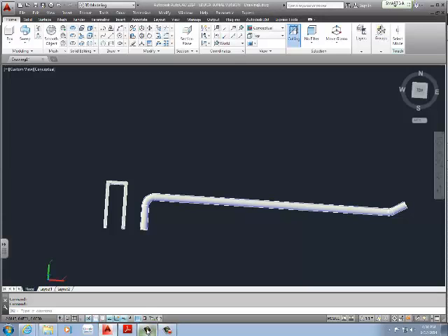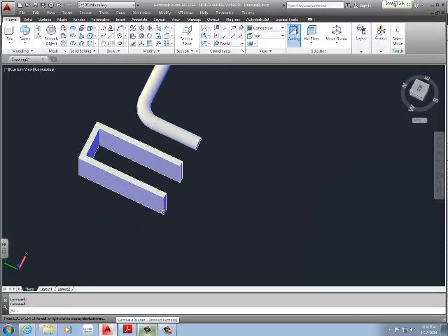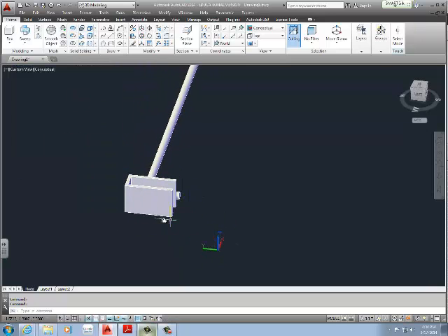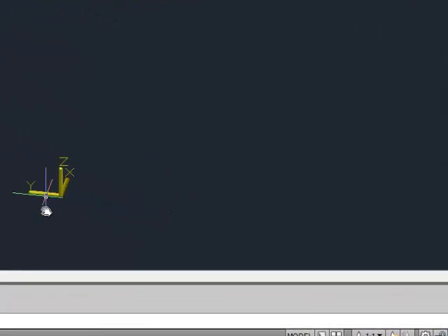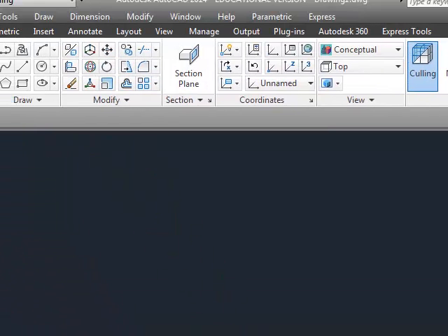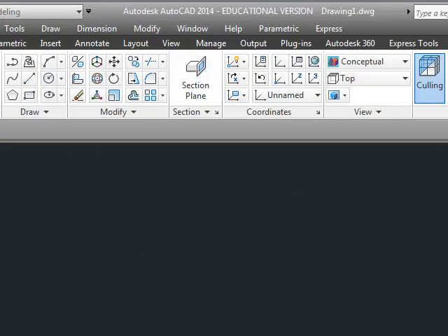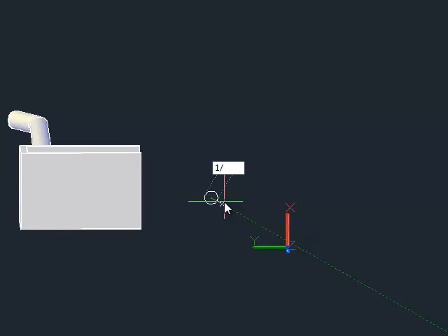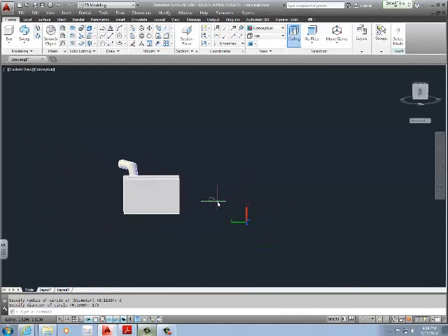So we go back to our drawing. You can start out with the actual hole. To do that, make sure you rotate in a direction so you can see the back. We also rotate our X and Y coordinate systems so that X and Y are facing us, so we can see both, not Z. And we're going to create a circle. Again, there's missing information about the circle size. The circle diameter is usually 1/8, because that's the wire they use to hang parts for powder coating.